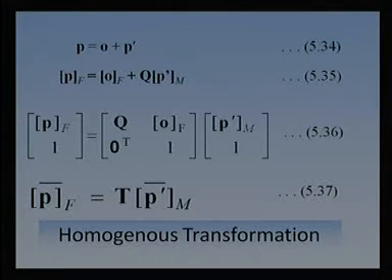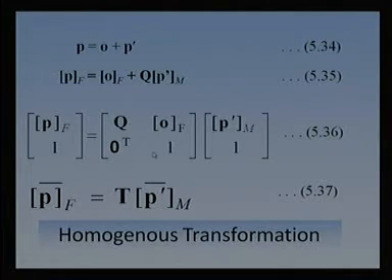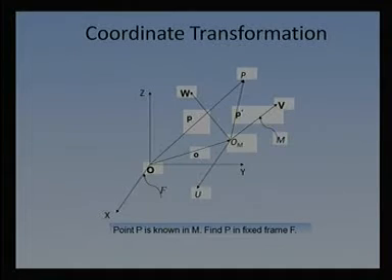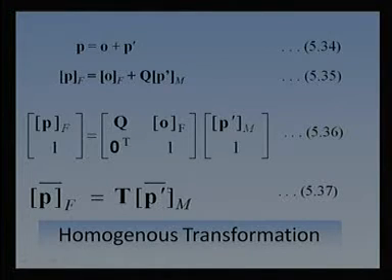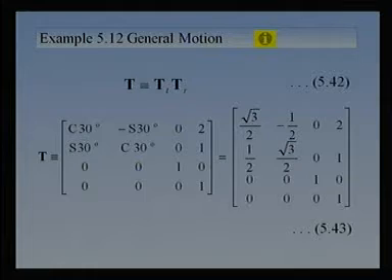You remember this lecture here, that was I think a couple of lectures before. We said if I have a point P and if I have a frame here, I can write the position of that point in the fixed reference frame using a homogeneous transformation matrix T, a 4 by 4. What does T do? T represents this point P and the orientation of this coordinate frame in the fixed frame. So, in robots we have several such frames. So, okay, we go back.